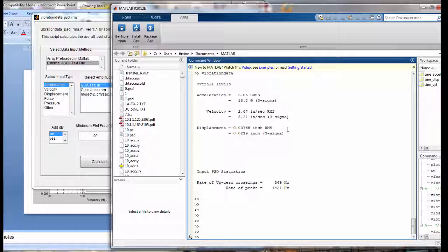But please keep in mind that in a shaker test system, as we're actually doing a test, we could get 4 sigma peaks or maybe even 5 sigma peaks. That depends in part on the duration of the test, and it also depends on how well the vibration complies with the ideal Gaussian distribution. And always there's some imperfections that come about in the test process. So we could have some deviations from the ideal Gaussian. So just be aware, for example, that you could have higher sigma peaks.